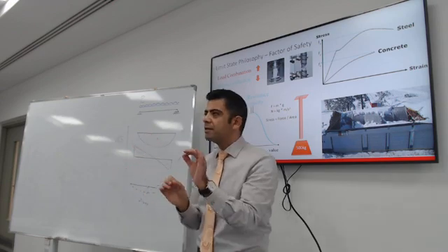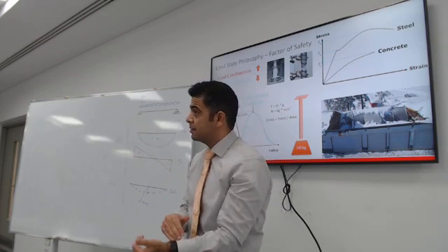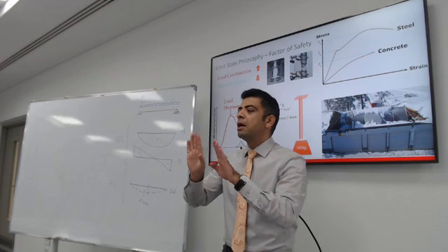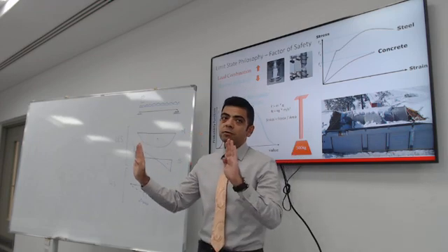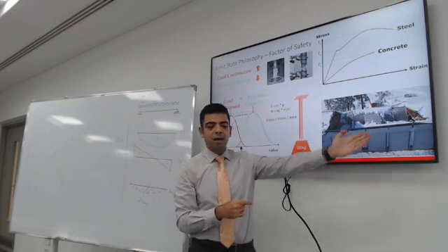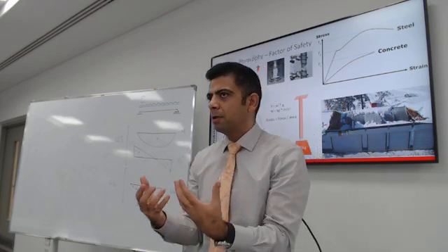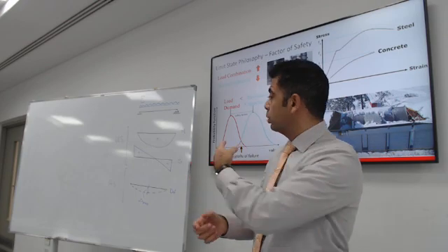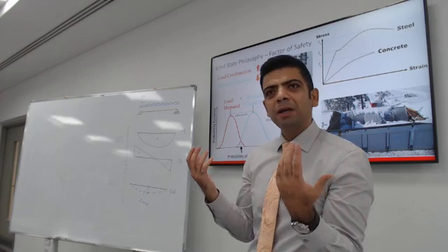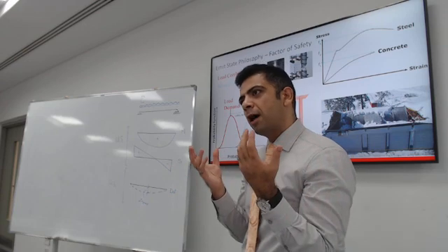Having said that, there is a chance that something might go wrong and the concrete cube achieves less than the design value. That's why we use safety factors, because I want to increase the load a little bit and reduce the material strength a little bit to create a factor of safety to avoid a scenario like this. So the more you practice and the more you apply the principles, most probably you will come and revisit this. It took me a while to understand this concept. Why do we increase the load? And how do you figure out if it is 1.4 or 1.5? How do they come up with this?